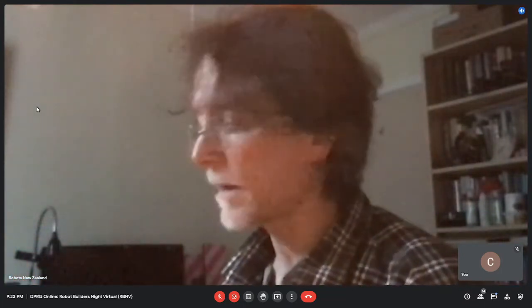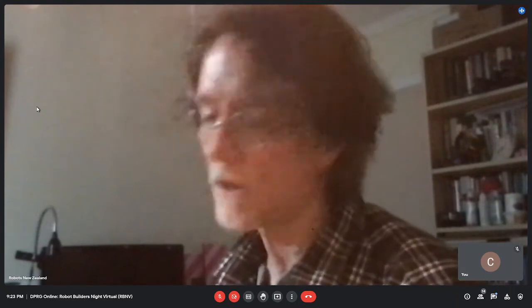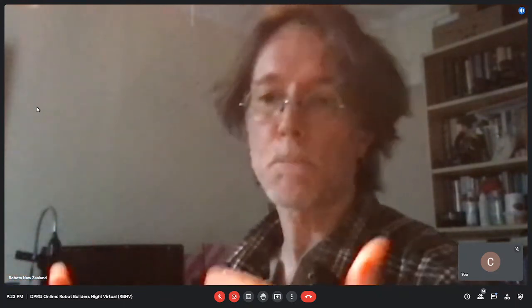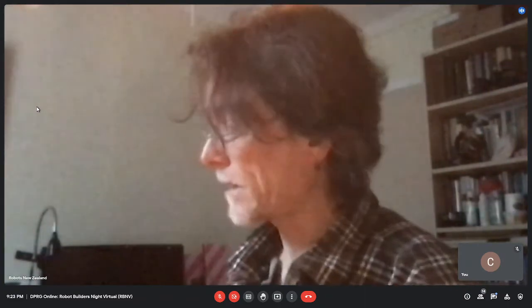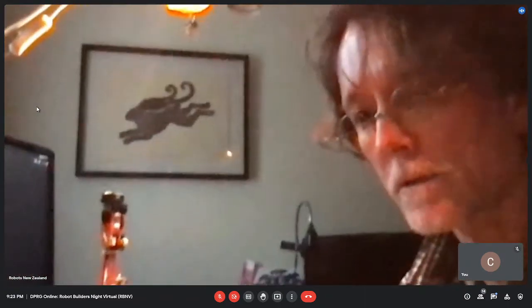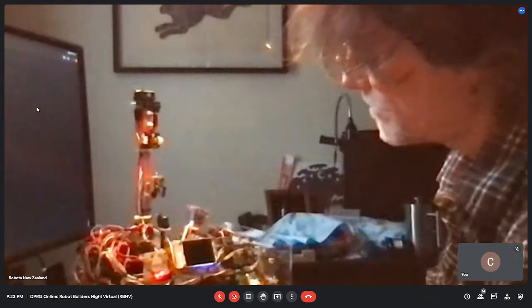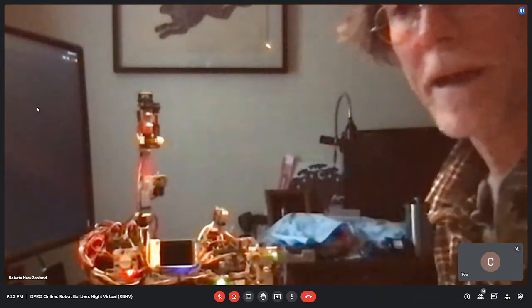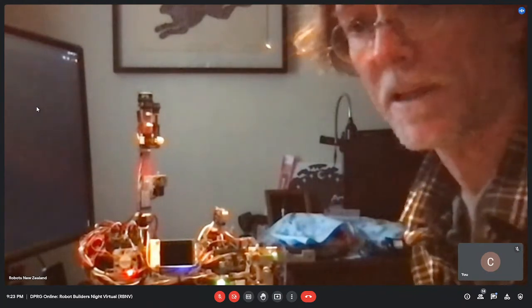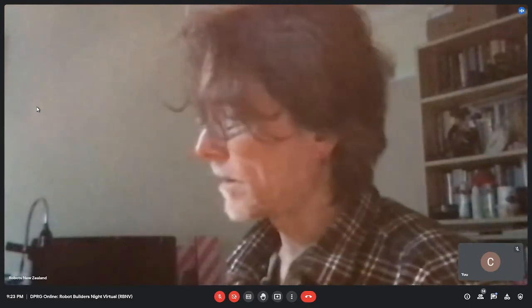So I'm pretty happy with that, and I think that hopefully I can maybe do an on-the-deck demo of this actually running. So I could run the robot towards a wall or something like that, and it would then back up, and then I could put something behind the robot. There are no bumpers behind the robot, so if it sees something while backing up, that's the highest priority. In fact, I've got this mast sensor right here, and if that mast sensor senses anything, it actually shuts the whole thing down. It just stops everything because obviously I don't want it to run into anything and damage the robot.